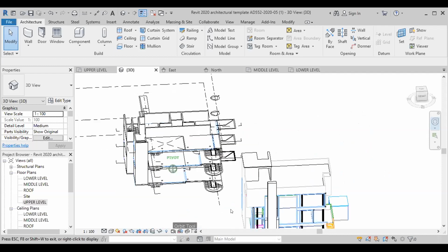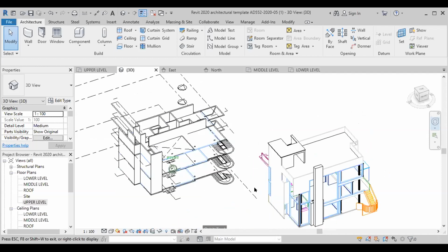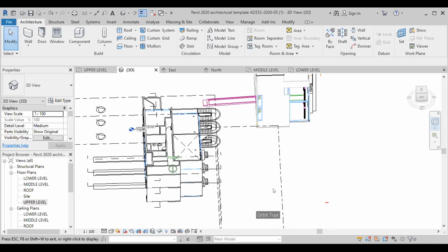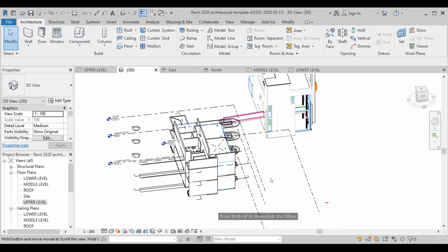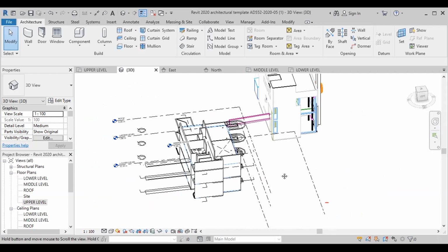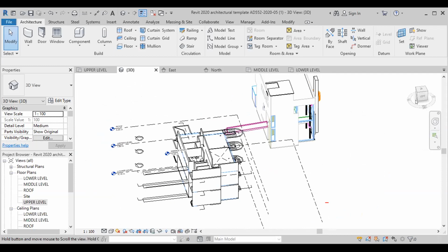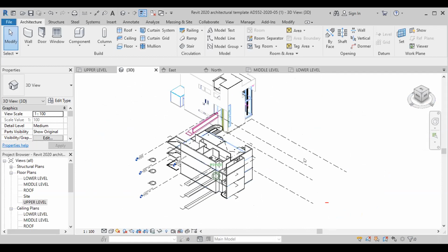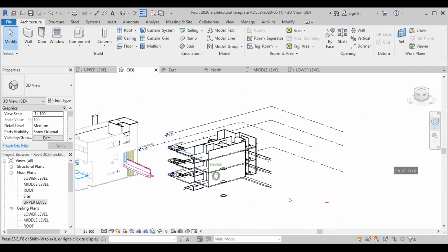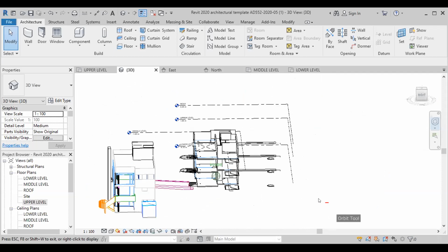Okay. You know, you still have these small walls here. You have to stop so I can annotate. Go to the opposite side, orbit to the opposite side. You can use shift and the middle of the mouse so you can orbit easily.